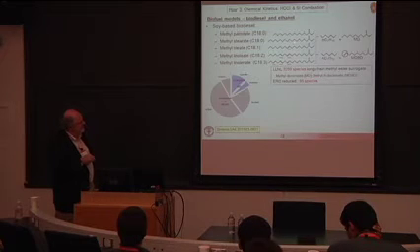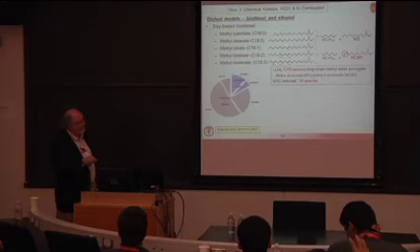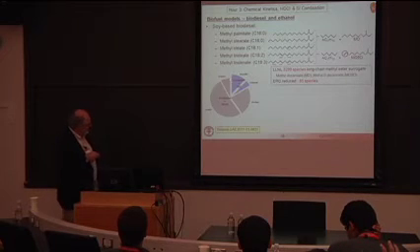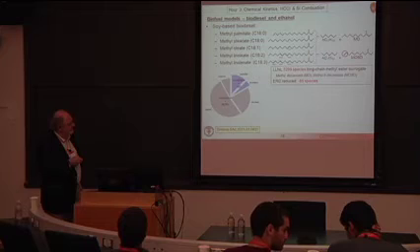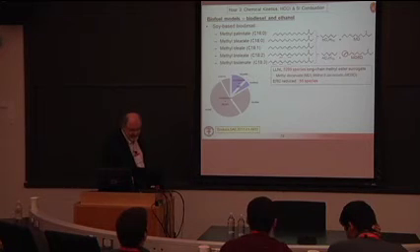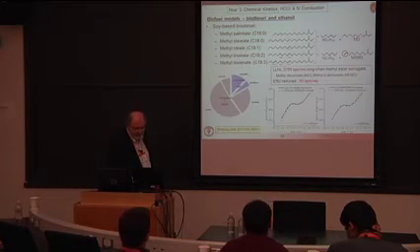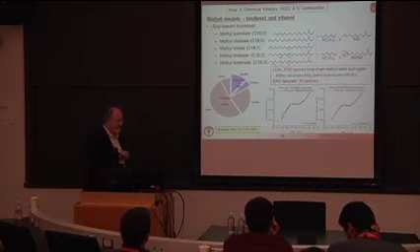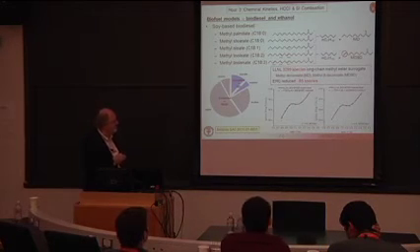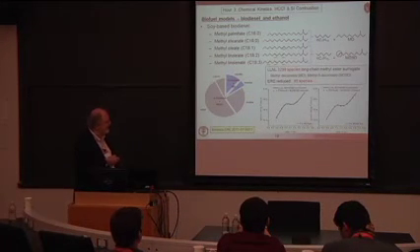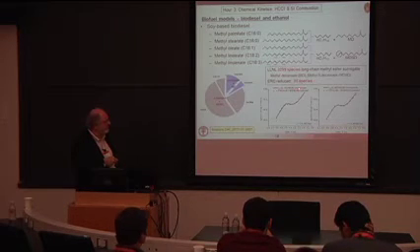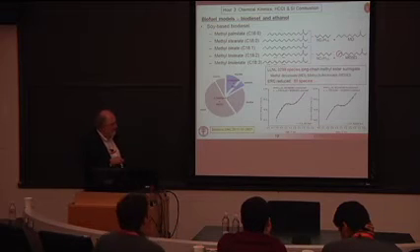And then for the unsaturated, again, N-heptane with the decenoate. So the fuel itself might consist of a certain amount of palmitate, stearate, and so on. And so this is how we break it up and represent that fuel. We're able to model that with just 85 additional species, but this includes some of the species that are already in the multichem mechanism. So when we were all done, I think it brought us up to 120 species total. And we're able to match the Lawrence Livermore mechanism with the multichem data.